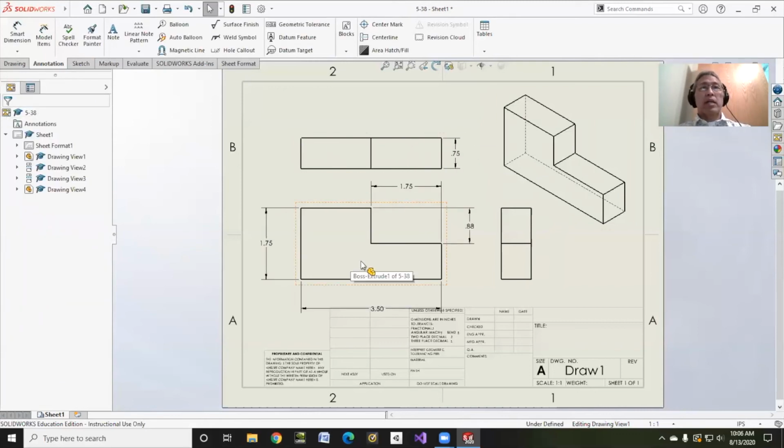Now, when I did my dimensioning in my model, I tried to make them beautiful like I would make them beautiful here, and that's how they kind of showed up. If you recall, or hopefully I've told you this already in another video, the distance from the object line to the first dimension line needs to be a minimum of 3/8 of an inch. And then every one thereafter, if there's more, is going to be a minimum of 1/4 inch.